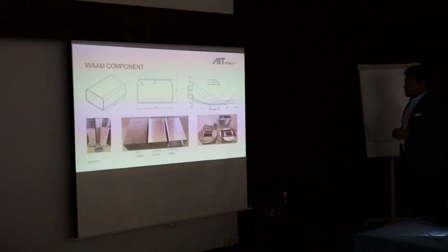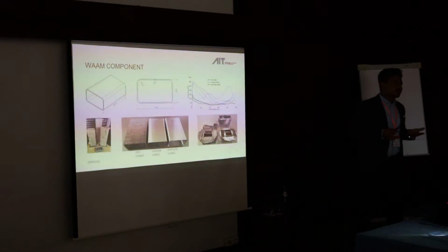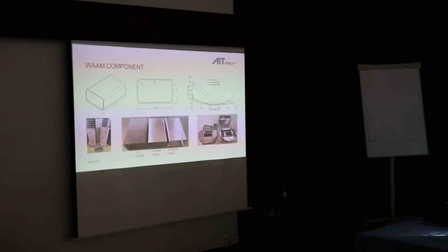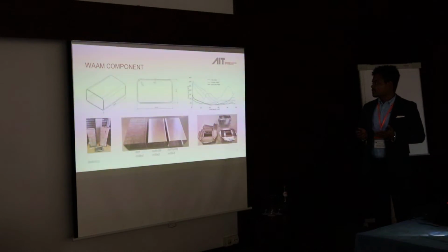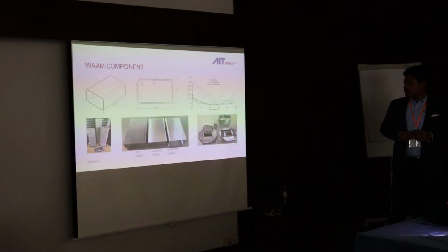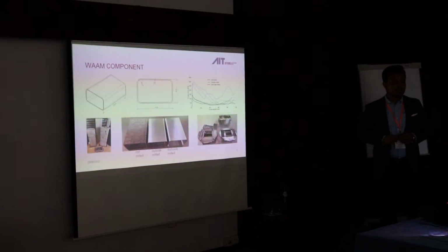We did the crash test. You can see the crashed profiles, at least one of each variation, and the force displacement curve. The result is not really what we wanted, because in a metallic material, when we have axial crash and we want the structure to absorb energy, we want nice plastic folding. Like a sine wave, each folding represents one wave, but here we didn't have that. That means we need to work more on the alloy, at least. We also saw that the one which was not milled was not really consistent, so the test data is not repeatable. The other two were quite consistent. So for the sake of simplicity, as a first attempt, I moved on with the third variation, the both side milled.